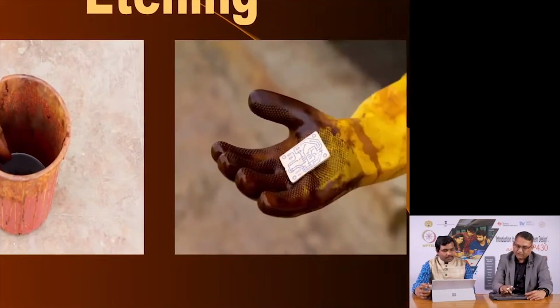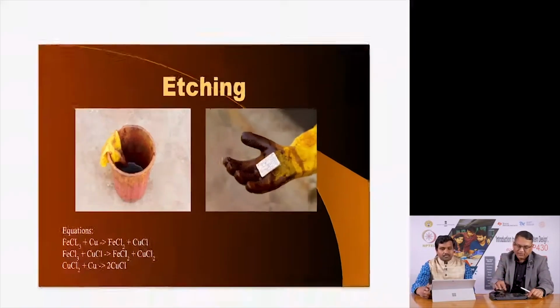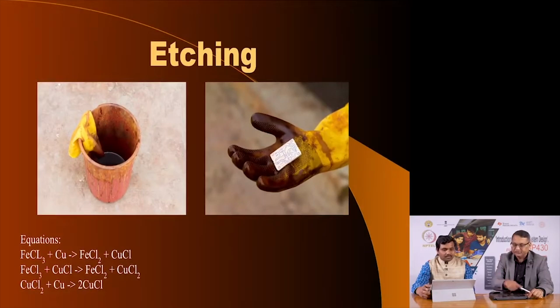We also have a rubber glove. This is important. You do not want the ferric chloride to come in contact with your skin, although it is not very harmful and you can always wash it off, but if it can be avoided, why not. So, you see the glove is used to handle the PCB as you put it in the etching solution.